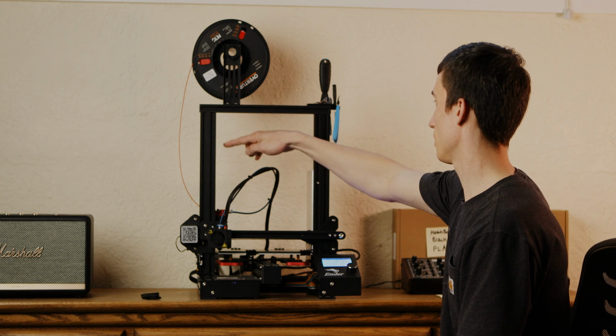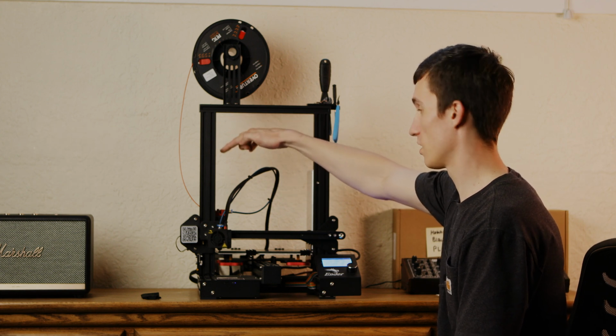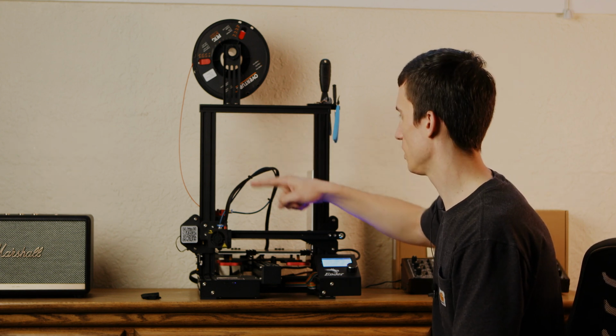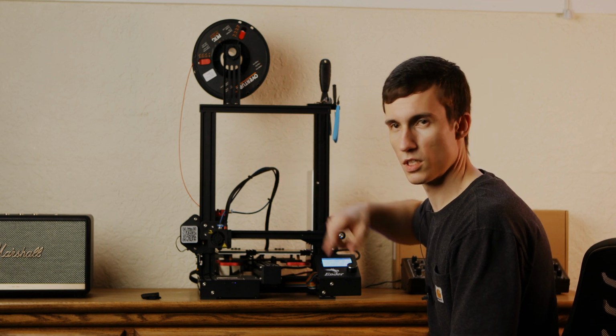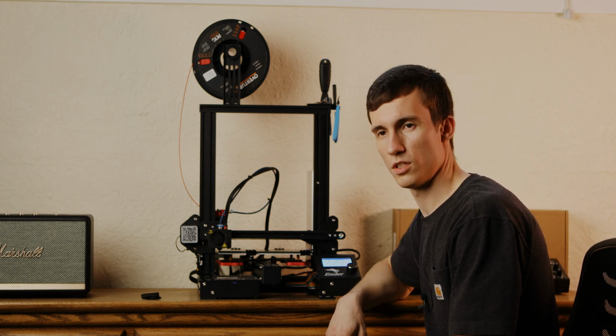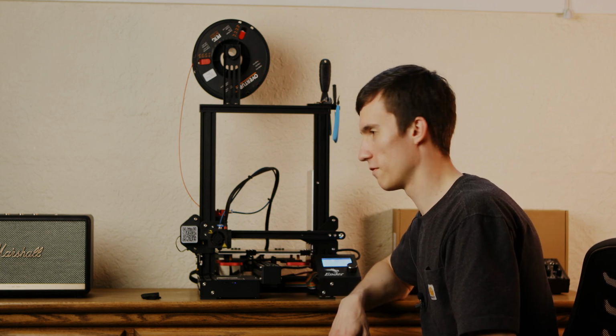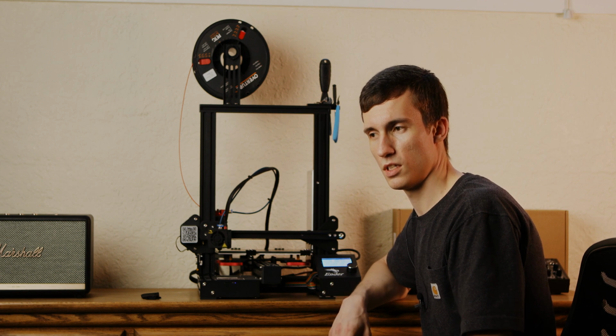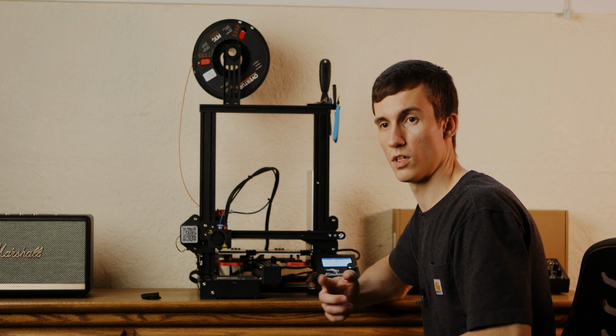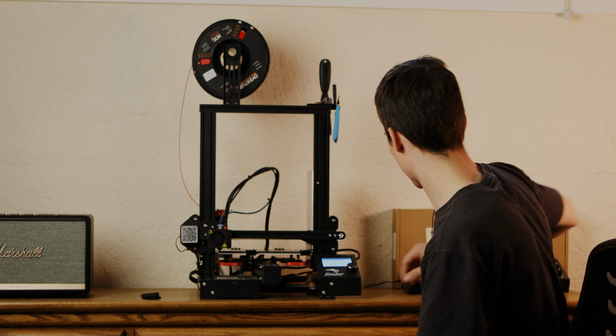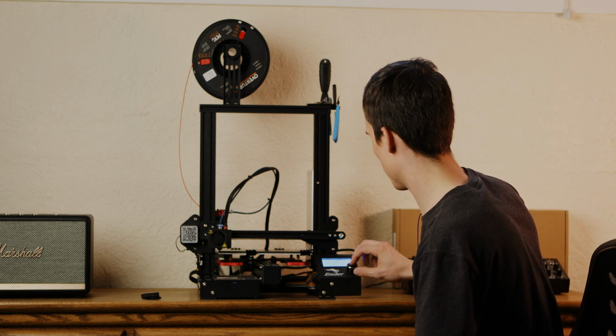I checked the Z-axis. It has been greased, and if you don't have any grease on the Z-axis lead screw, potentially what may happen is you may have issues with the different steps with the layers. You'll have parts that are thin, parts that are a little bit thicker than usual because it couldn't lift it or it lifted it too far. So I'm going to start this print.